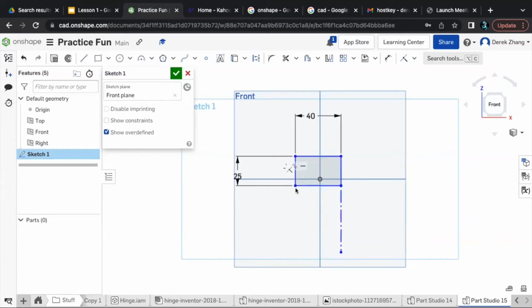All right, so next we're going to teach you how to make these lines black. First, go to this corner again and click that. Now you're going to click the letter I. This is another very important tool called coincident. Basically, you take this point and you can connect it to anything. Let's say you have a rectangle and you want to connect it to a line. You use the coincident tool, click this dot, and then click the line, and it'll merge them together. So click on that box, and now you're going to hover over with the plus symbol.